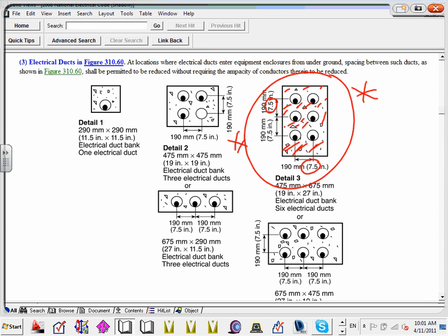You put them in PVC conduit, they put them in a spacer, and they put concrete in between them. They space them and pour the concrete right in between them. And it becomes concrete encased ducts. And they pull the conductors through them and put them underground. Different application, look at this, you can put them in any application, as you guys can see.